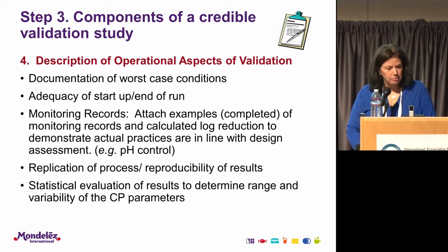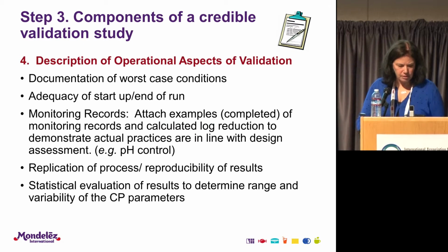The operational aspects of the validation, you have to document your worst case conditions. And then you need to put in there the adequacy of the startup and the end of run. Your monitoring records, attach examples and completed examples of monitoring records and calculated log reduction to demonstrate the actual practices are in line with the design assessment.